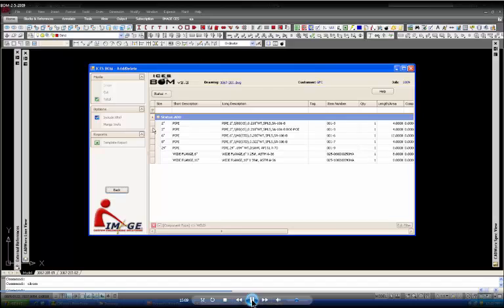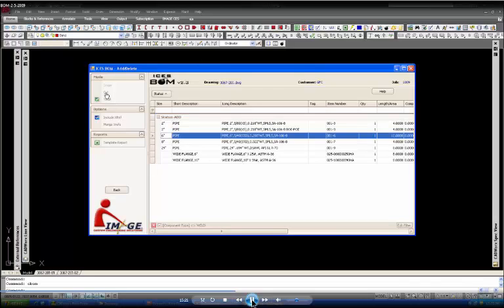Okay. Now then, so there we have added. We've got 4 foot, 4 foot, 12 foot on the 6-inch pipe. What happened there? We've got actually 3 runs of 6-inch pipe, so it's added all those together into a single line. And then the wide flange, that 6-inch by 20 pound, that is the top and bottom flange.